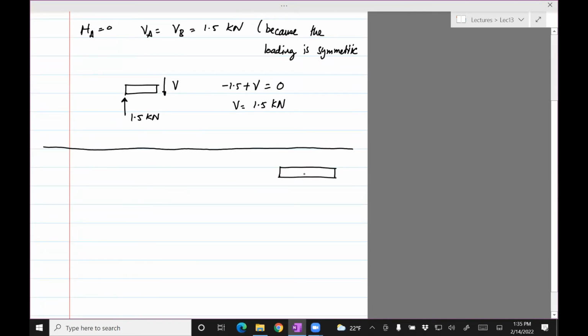The top beam, this is joint A. The formula we want is that shear stress at joint A is VQ divided by I times B. V is known, it's 1.5. I is the inertia, which is always about the centroidal axis, and that is given to us.